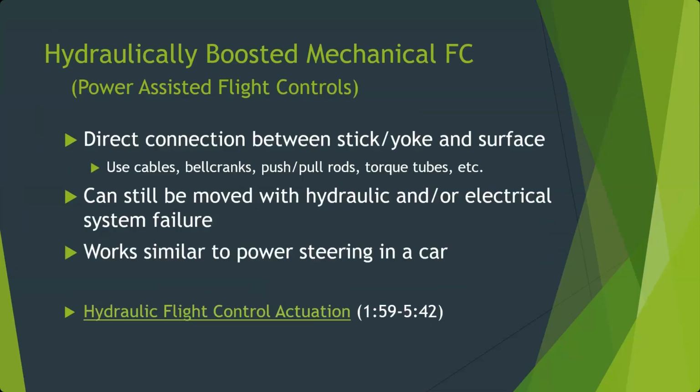The crew, or whoever is moving the flight controls, is going to have to overcome a lot of opposing forces, both from the size of the flight controls as well as the air stream across them. The more you try to deflect a flight control at high speeds, the more air is pushing against it. But these work similar to the power steering in your car, where even if you lose hydraulics or electrical, you can still move the flight control, but you're going to have to work hard to do it.